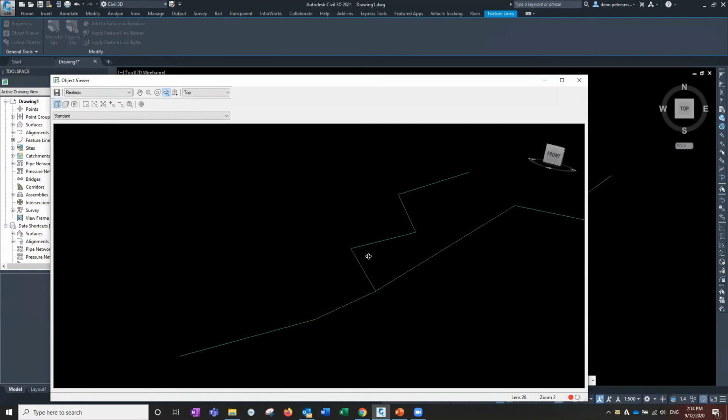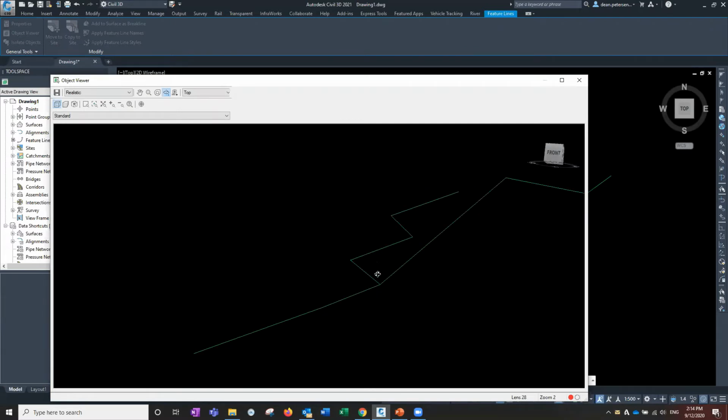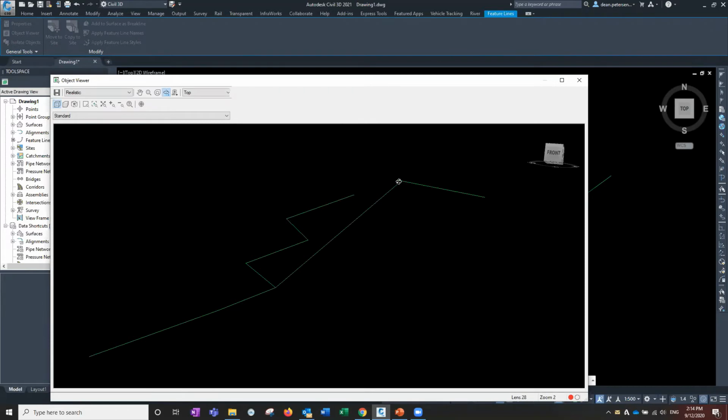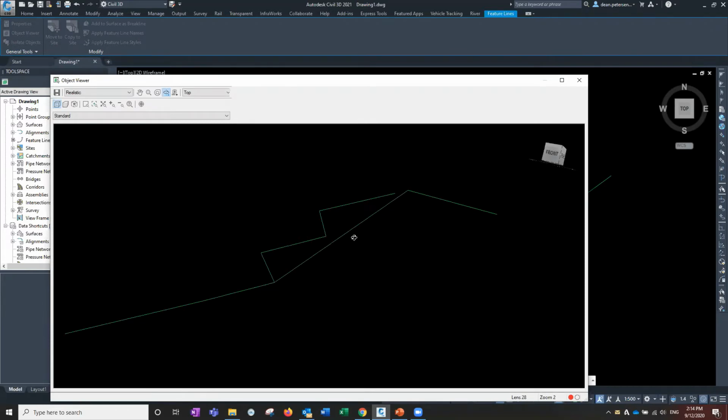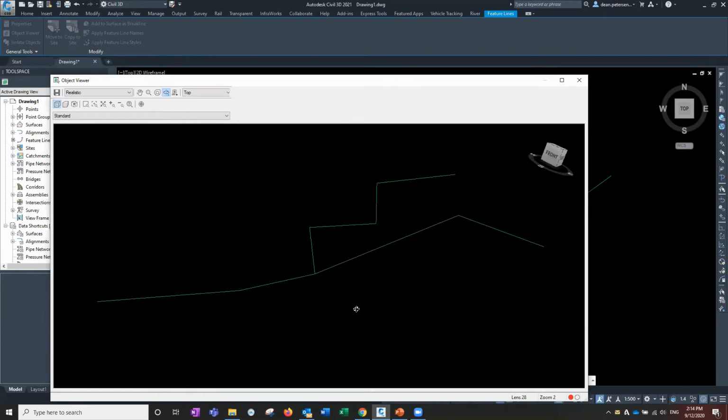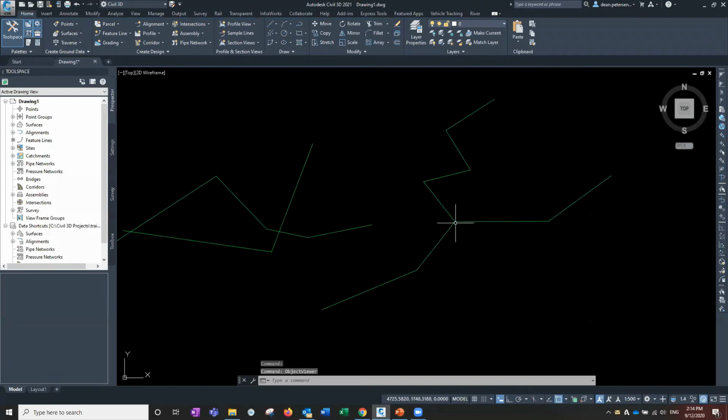Now, we should find in the object viewer that there is our polyline that has the 50% grade there, running down, down, down, and the 50% grade continues along another feature line down there. This one's back at its original elevation at 0. It just snaps into it. So grading along multiple feature lines is what it does. And just make sure, obviously, as I found out just then, to snap the two ends together.